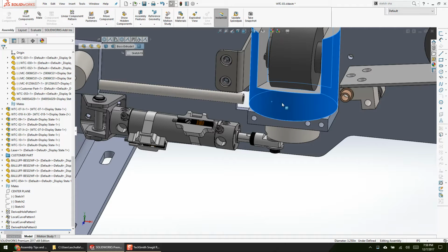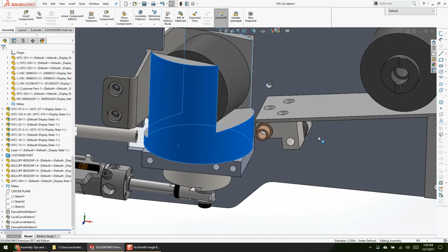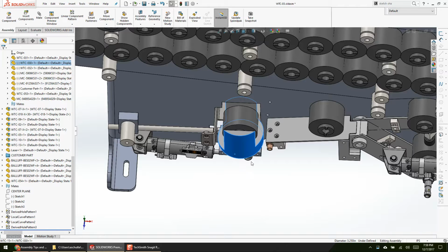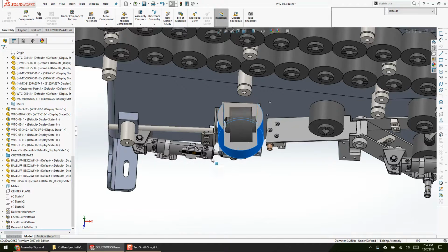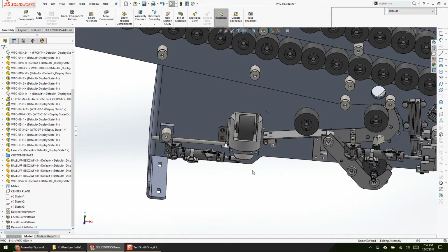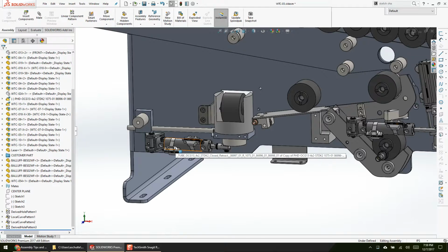It makes for a pretty picture when you're doing a design review and the customer can't visualize how the roller is going to end up down the good part chute. And you're like, okay, click, flexible, and the customer's like, oh yeah, that's cool, right? That's the goal. So we've got patterns, MultiMate to eliminate mates, make virtual to eliminate unnecessary components on the hard drive and make SolidWorks faster and more reliable.